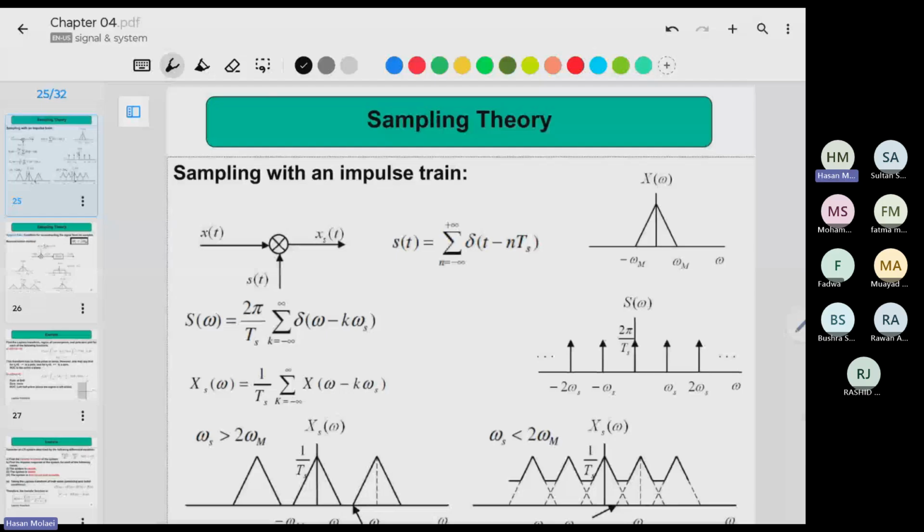When you have an analog signal, if one small noise affects it, your signal is changing. But in digital, you have 0 and 1. You can put a threshold. For example, if you consider the voltage less than 1 volt as a 0, more than 4 volts as a 1, which means you have a big margin for noise.